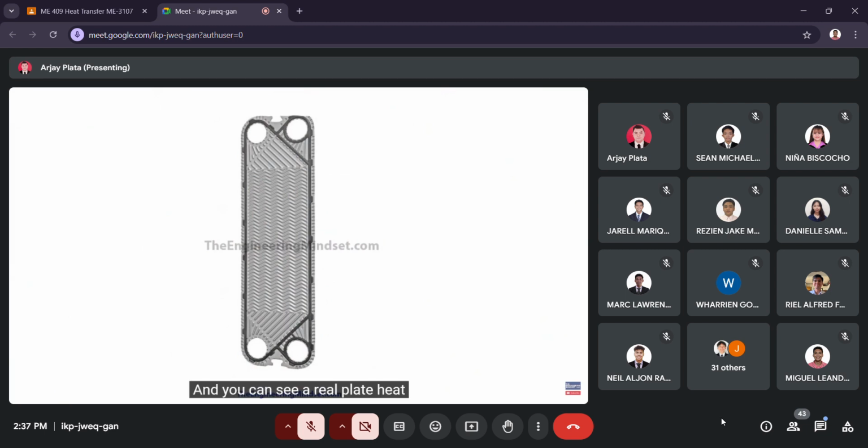Now you can see a real heat exchanger plate there on the screen. These are typically made from steel or titanium, and you can see they've got this pattern grooved or stamped into them. These patterns are going to strengthen the plates, which are obviously incredibly thin, and they're also going to increase the heat transfer surface area, as well as creating a very turbulent flow inside them. So it's not smooth. All the water has to rumble across these and come out very rough and turbulent.